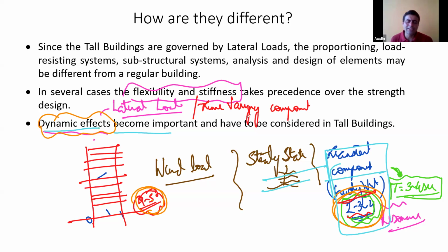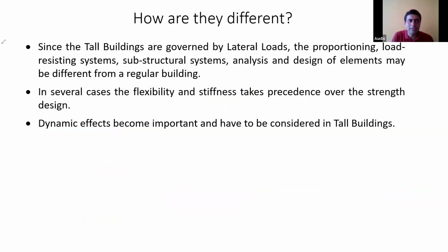Now, why am I not taking seismic in this? Because seismic is usually always a dynamic load, which is an inertial load changing with time. So I'm not considering seismic much over here. I'm focusing more on wind because wind has these two components together, steady state as well as the transient component. So therefore, I spoke more about the wind in this case. I hope this is clear.